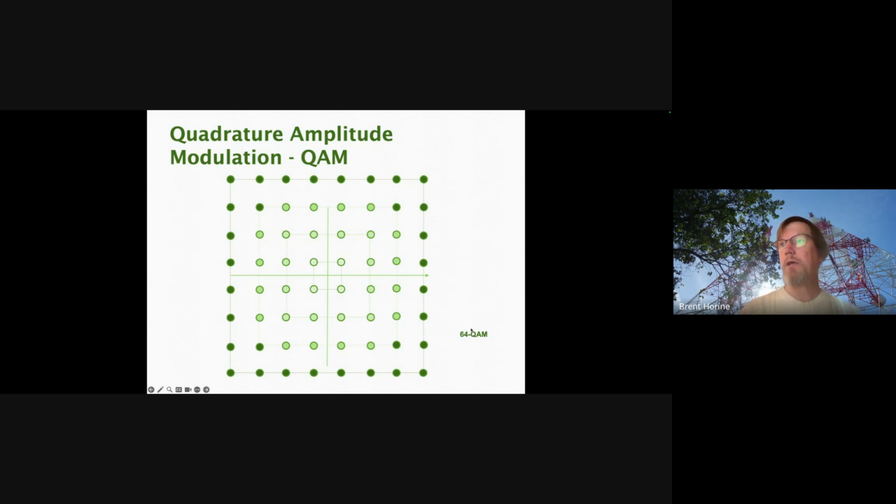So now here at 64, what's log base 2? 64 is 6, I think, right? Yeah. So each one of these constellation points, you're sending 6 bits of information, right? If you go to 1024, that's 10 bits of information that you're communicating using one constellation point.